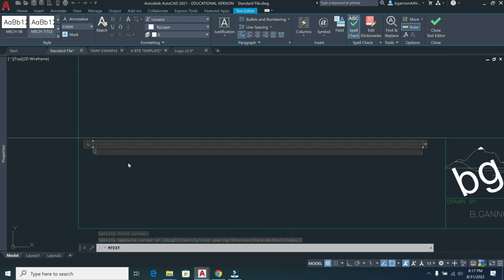But general notes, and this is going to all be capital letters because all of our drawings should be capital letters. And then 1 space, okay, then remove all burrs and break all sharp edges. 2, unless otherwise.